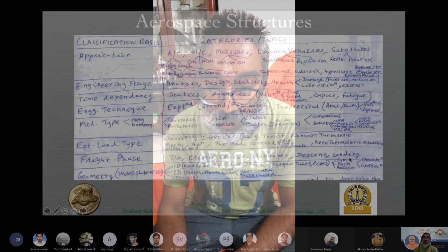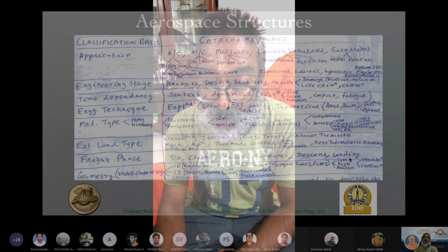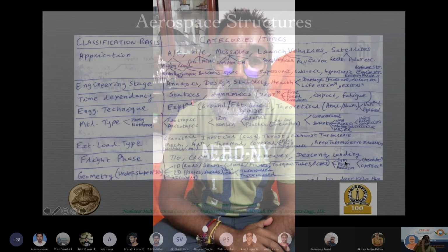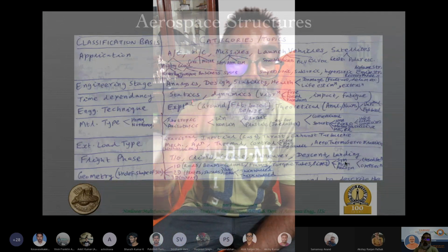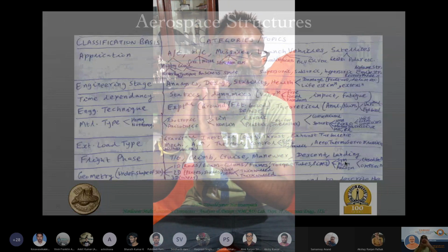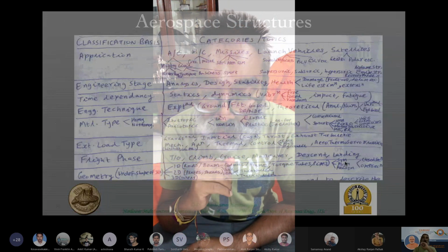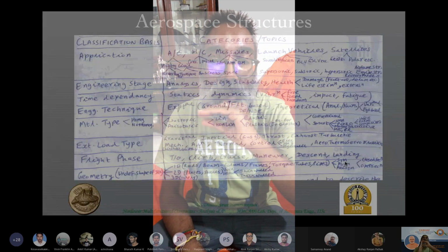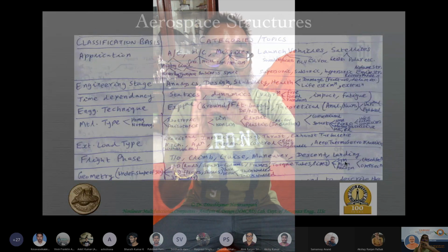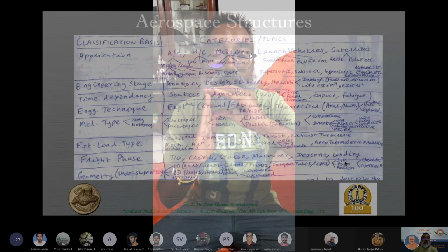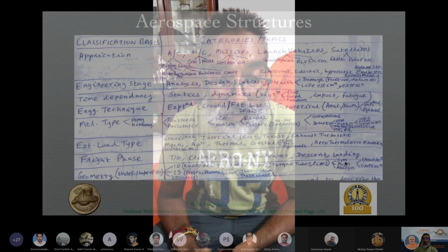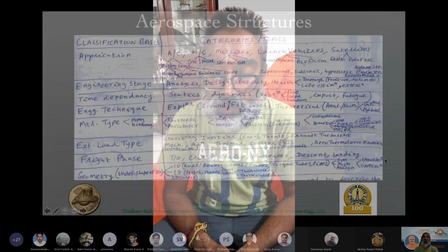Then again, in terms of the 1D structures, you could have cross sections which are symmetric, like in the case of an I section, or asymmetric, in the case of a channel cross section. It might be symmetric in one direction but asymmetric in the other direction. Then you could have axisymmetric, like in a shaft, which is a thin-walled circular shaft, or it could be even a rectangular box beam which is within, let us say, the wing. It's called the wing box. So these kinds of structures could be there where you can utilize certain symmetries that are involved in certain situations.